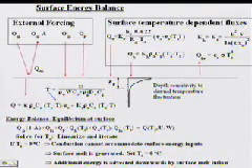We don't keep track of the temperature of the snow as a state variable per se. If you remember on the previous slide, I just had water equivalent and energy content. Well, this equation shows how the energy content is related to the temperature. Basically, the energy content is defined relative to 0 degrees C, the melting temperature in the solid frozen phase. So if the energy content is greater than that, the amount of water that energy can melt is present in the snow.